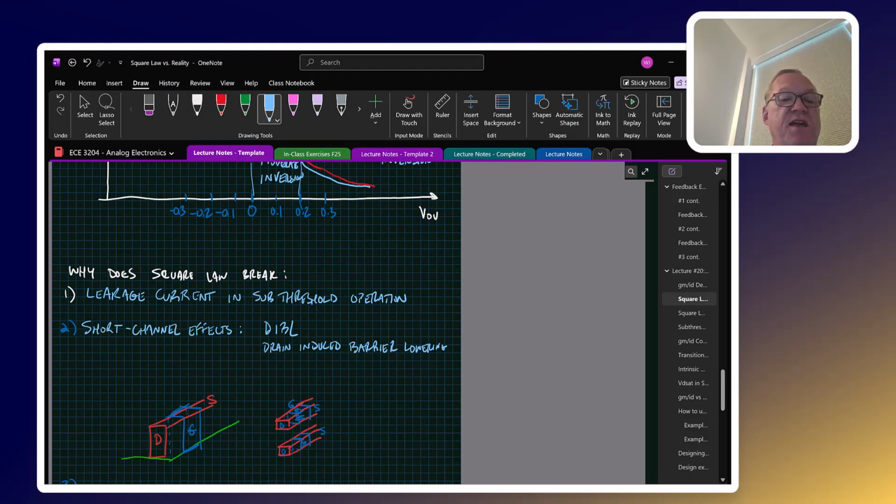Additionally, in order to regain control of the channel and to make it perform the way that we expect it to as a transistor, over the years, they've had to dope the channel, and so they increase other physical effects that cause us some problems. Now, as a way to try and get control of the channel back, they have introduced FinFETs recently, and increasingly they're going to what are called wraparound gates, and I have some 3D drawings of these things right now.